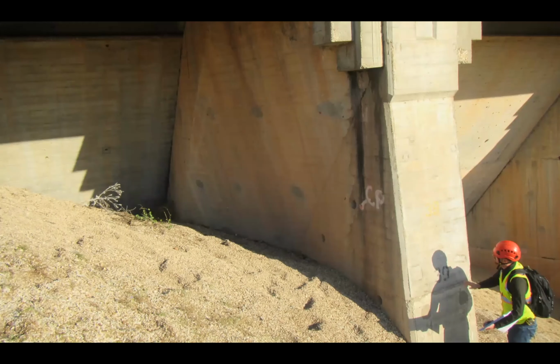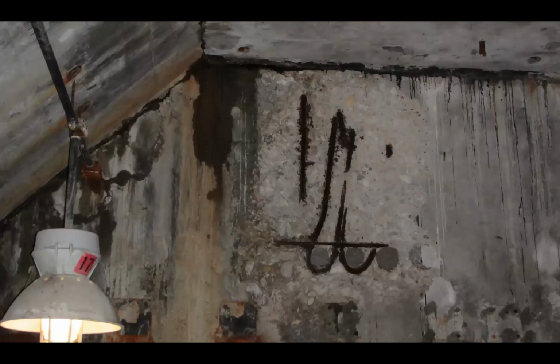And you're documenting these particular conditions that you're seeing, because that's going to inform the condition assessment process when you're done with the inspection. On the inside, you might see concrete spalling, delamination. This happens to be at the edge of a buttress on the inside. As you can see, the corrosion activity of the reinforcement is causing concrete to spall and delaminate. Or you might see exposed reinforcing steel. It's not a particularly troublesome condition, but worth documenting. You do notice there's some water infiltration through cracks as well.